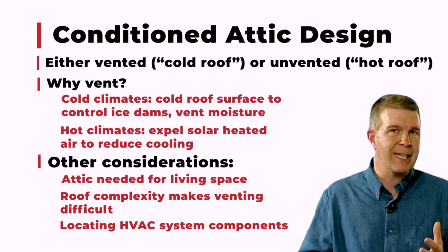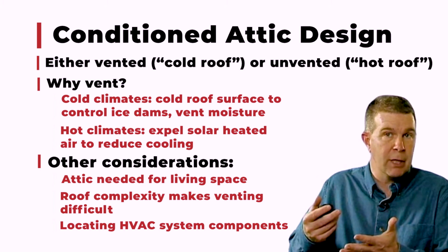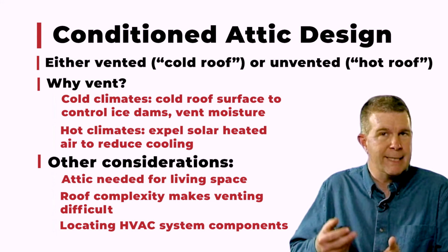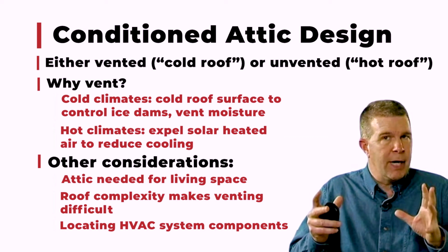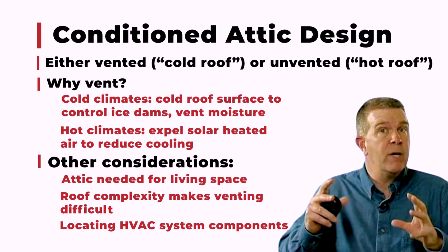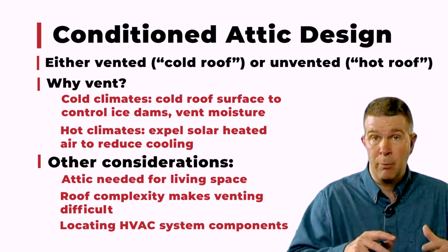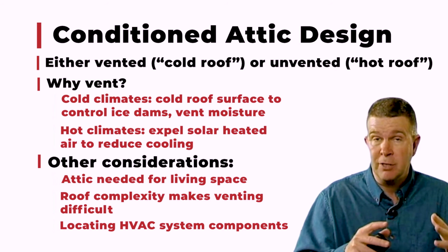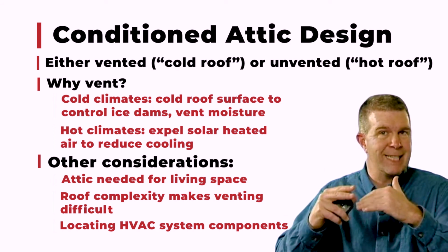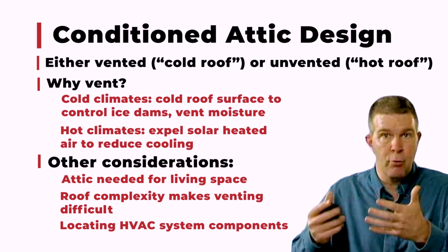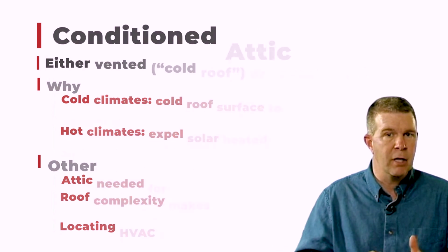The reason we ventilate a roof assembly, not ventilate the attic, but ventilate a roof assembly, is because we're trying to promote drying. It's a wet-dry issue, not a hot-cold issue. So it gets a little confusing, but you have to understand we've got two areas where we're talking about potentially ventilating. One is the attic itself, which could be ventilated or unventilated, and with a SIP roof, it's going to be unventilated because it's now conditioned space. And then on top of the roof, we can ventilate the roofing assembly or back ventilate the roofing material, if you will. So there's two different areas of ventilation, and you have to keep the two separated.